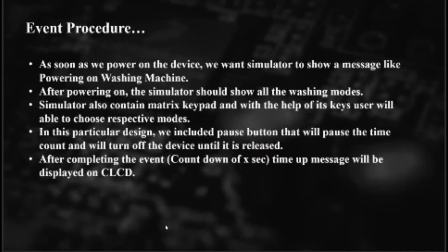And I am going to explain how we want to show the output in the PIC16F877A microcontroller. As soon as we power on the device, we want the simulator to show a message like powering on washing machine. After powering on, the simulator should show all the washing machine modes. The simulator also contains a matrix keypad, and with the help of these keys, the user will be able to choose the respective modes.